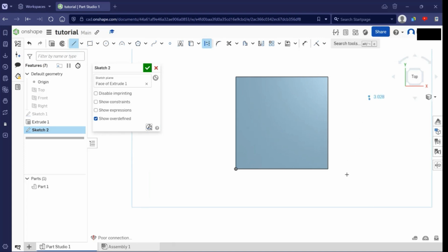Now we have lines that are dashed like this, and this will not appear when we do extrudes and stuff. That's pretty helpful. To remove a line, we could just press escape. So what do we want to do? We want two lines to run from the midpoint of this one and this one to create an intersection in which we can then put a circle, and then that would be perfectly in the center. So how do we do that? Once we get our crosshair close to the midpoint of this line over here, you can see that little box on the bottom right of my crosshair.